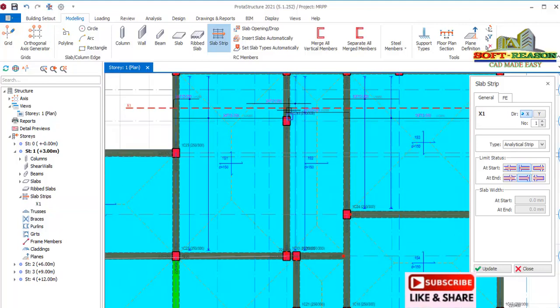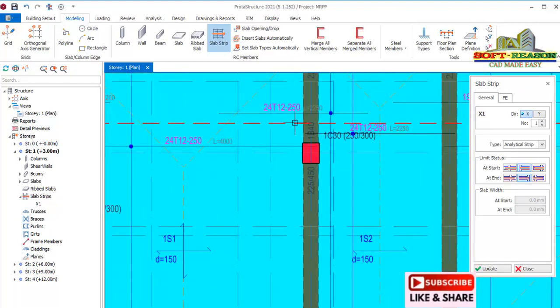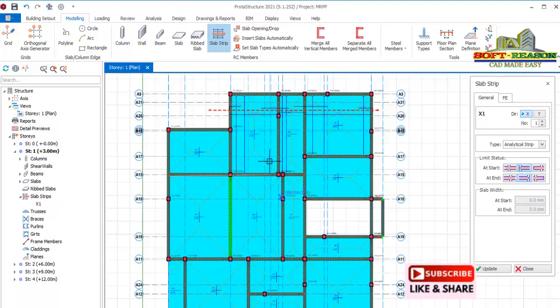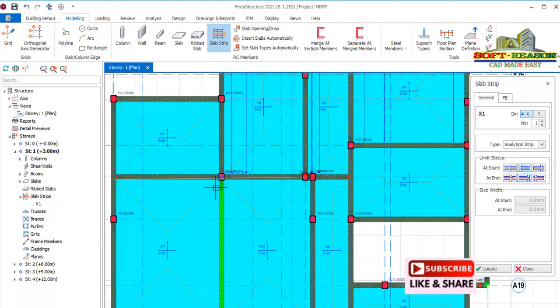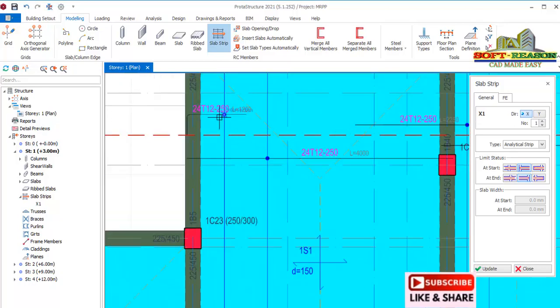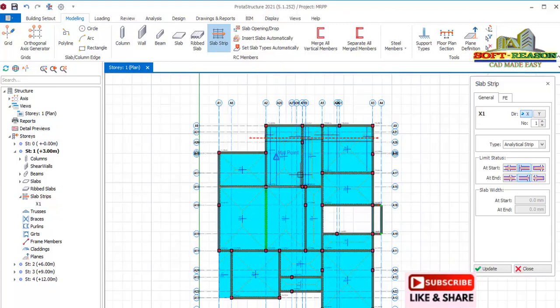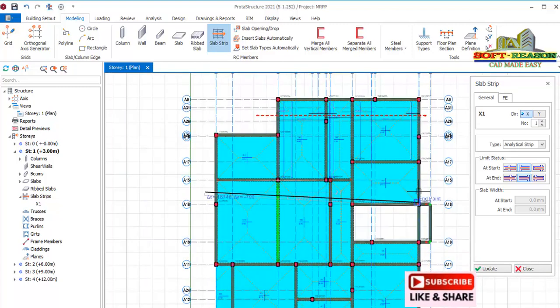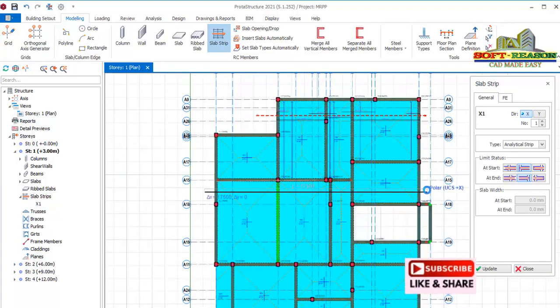All right, this one spanning from this point to this point. You are having 24 of these at spacing 250 right there. Okay, but for this spacing you can also make an adjustment depending on what you want. All right, so also the top and bottom bar have the same spacing. So we'll continue to place the strips right away. In these provisions, we'll have a strip here.